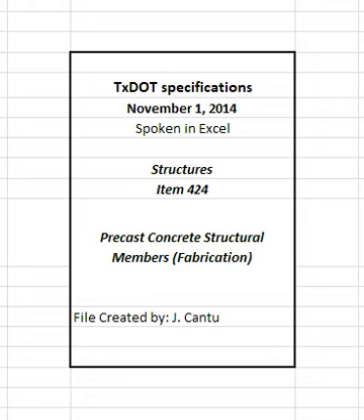4.2.5.3.3 Vibration of self-consolidating concrete, SCC. Vibrate SCC only when approved by the engineer. Provide an adequate amount of viscosity modifying admixture, VMA, in SCC mix when internal vibration is allowed by the engineer.